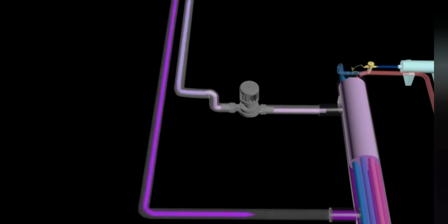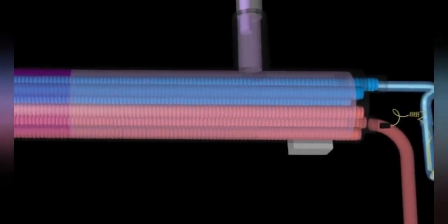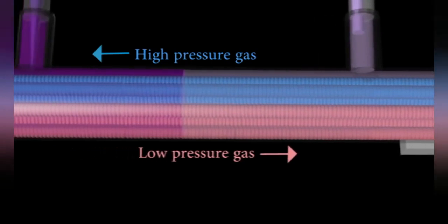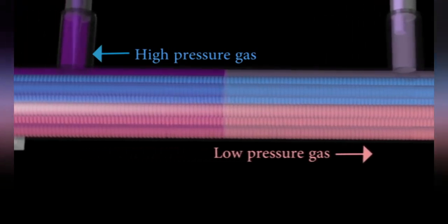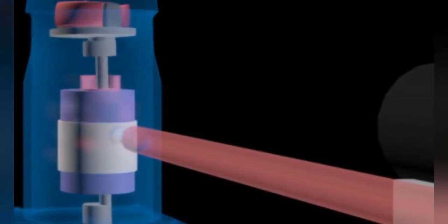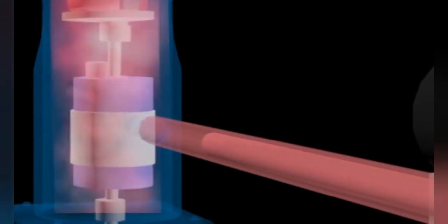When the liquid refrigerant with low temperature and pressure absorbs heat from the chilled water, the refrigerant will evaporate to low-pressure gas. The evaporator most commonly used is shell and tube type, where the refrigerant flows in the tube and the water floods the shell. The evaporator is insulated to reduce heat transfer. The refrigerant in low-pressure gas will return to the compressor and continue to the next cycle.